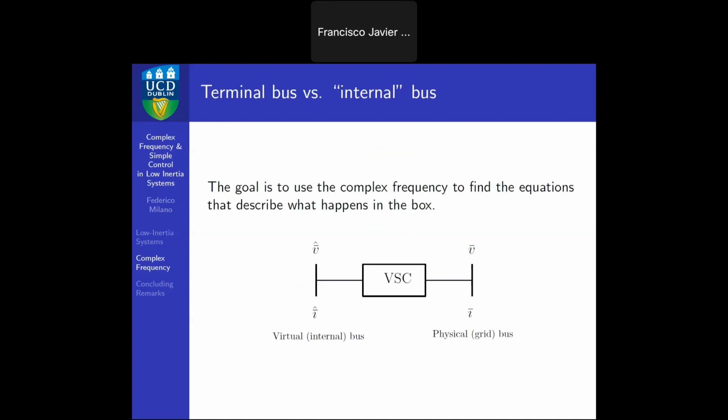Because then I say, okay, now we do this exercise of saying that I have an EMF behind some reactance. The reactance is something that can be defined based on the control and the model. It's not a physical thing most of the time. It can be virtual, of course, and this is not existent necessarily. Is this internal EMF I need to take into account, so a sort of series connection.